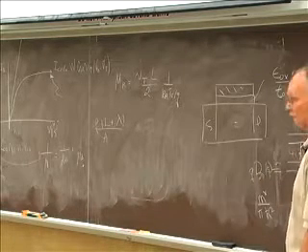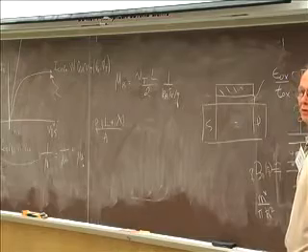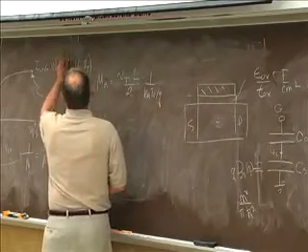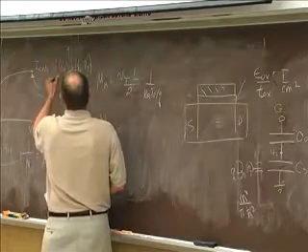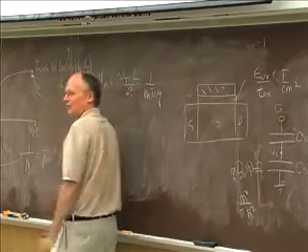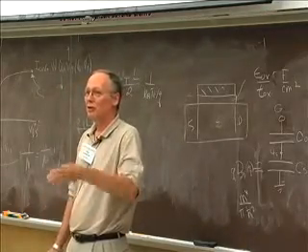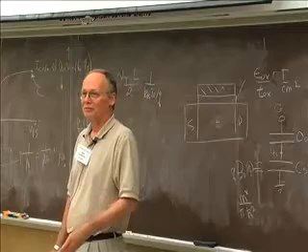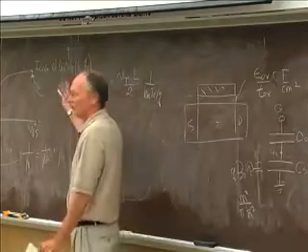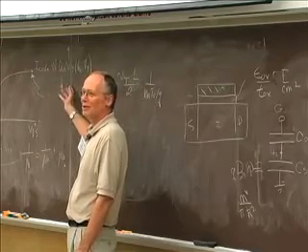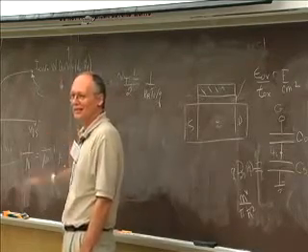So if I put these two capacitors in series, it's going to lower the overall gate capacitance. So there's a trade-off. The boost that you get from the light effective mass is offset to some degree by the drop in the gate capacitance. Your charge is going faster, but you have less charge. So the net effect is that you get a benefit, but again, you don't get quite as much benefit as you might have initially anticipated.